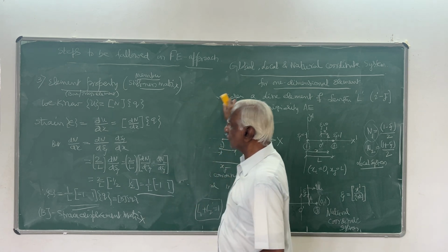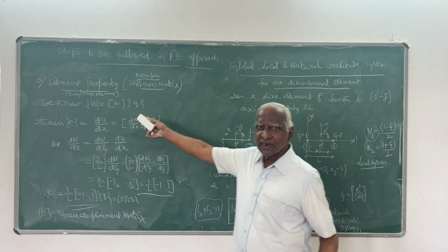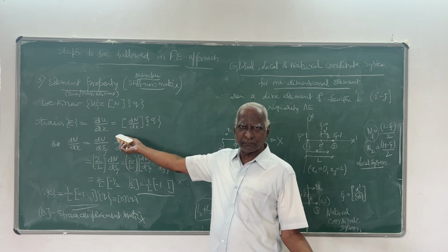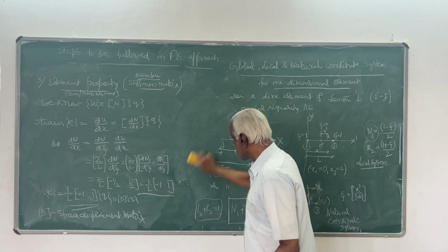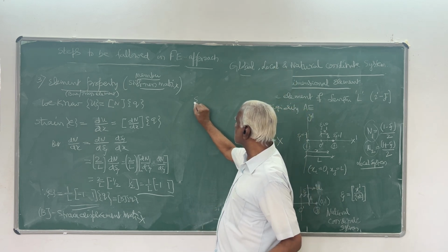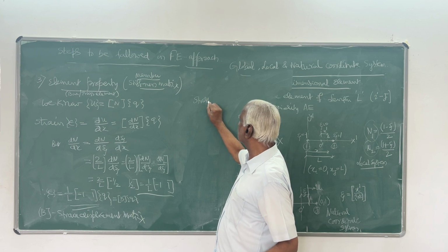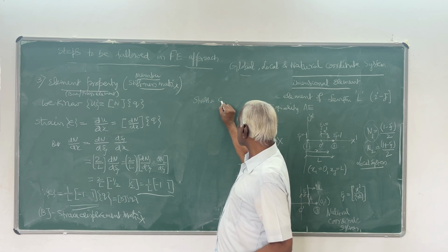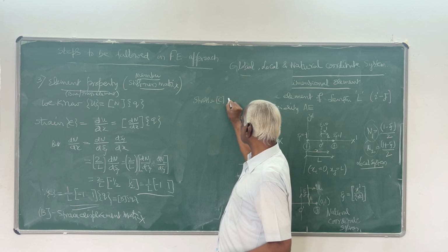Very simple. After knowing the shape function, the displacement model you will write, then strain. From elasticity, you write the expression for strain. Then stress, within the elastic limit, is the constitutive matrix into strain.